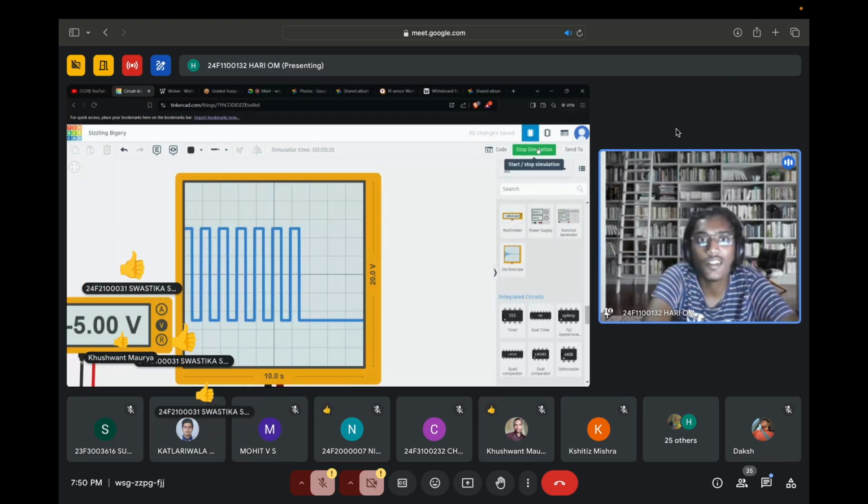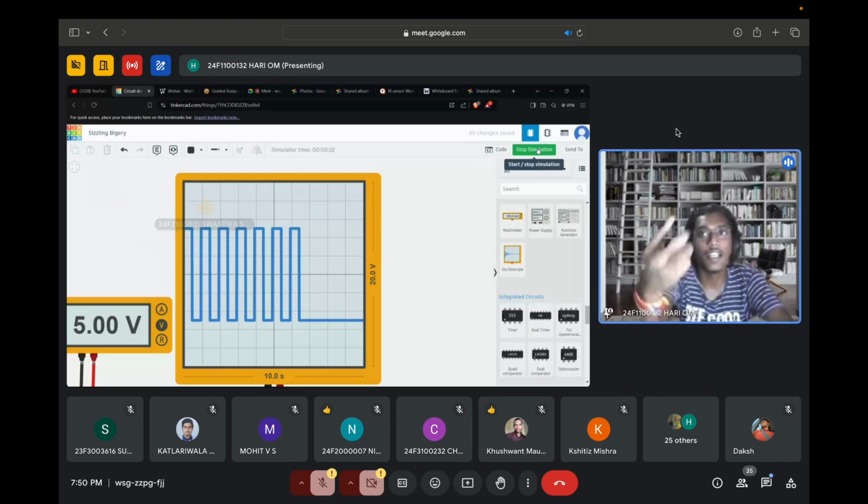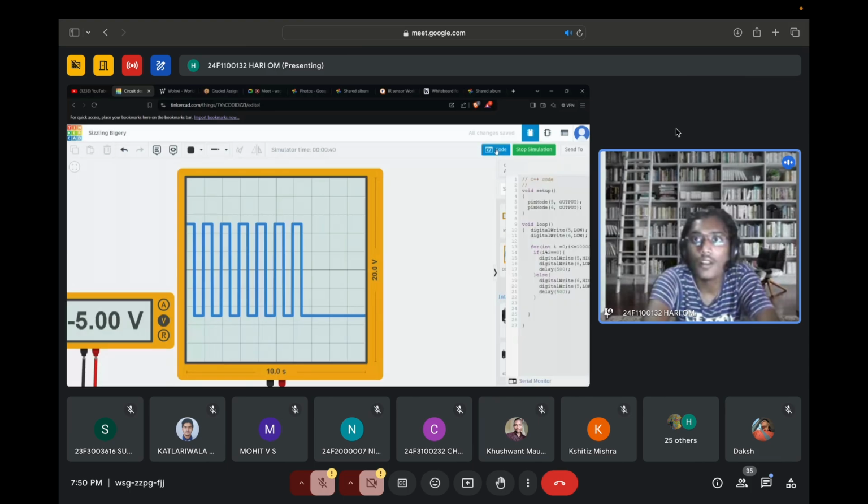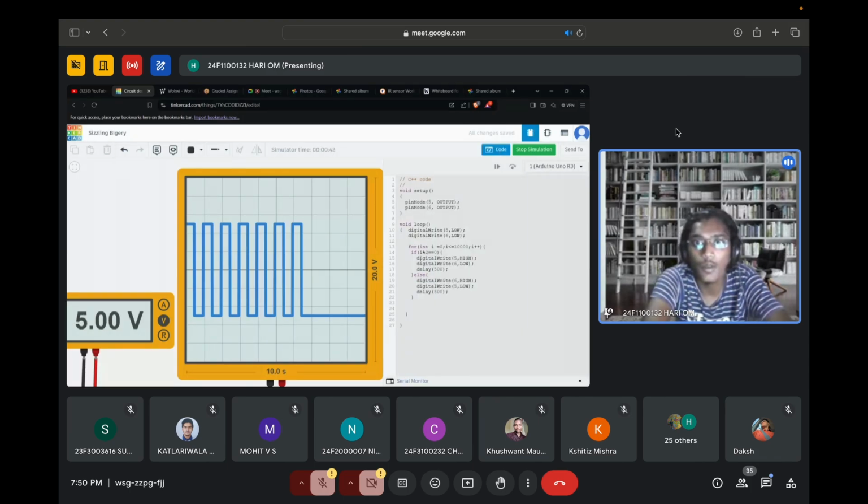Okay, let's generate. So in ADALM1000, you just set the wave, set the amplitude and set the frequency, and you will get it. And now you are creating some square wave by your own. And one thing I can tell you, you can change this code from digitalWrite to analogWrite, because we are using a PWM pin. Then you can set this high voltage between 0 to 255.